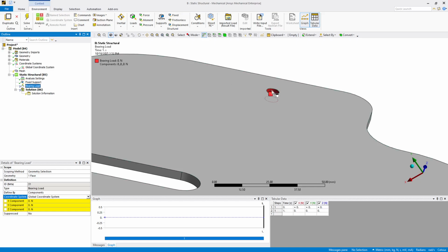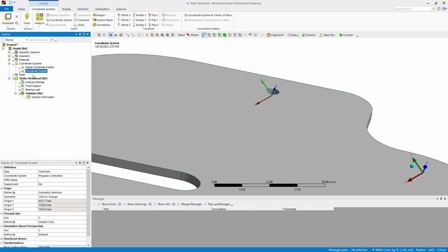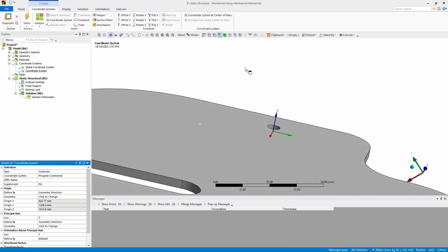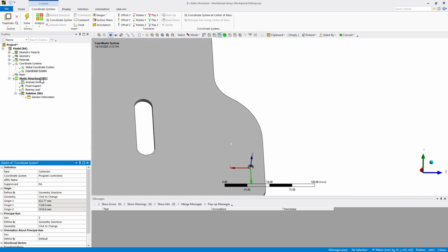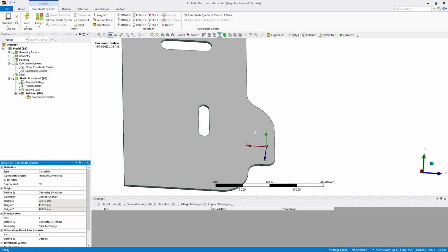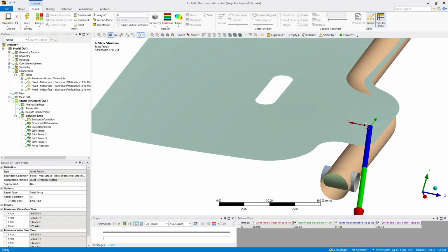So if I pick that face and insert a coordinate system and then orient the z-axis to be normal to some geometry, like this face here, we now have the same coordinate frame, except I need to flip z, and then X is toward the inside and Y is up, and that matches this joint coordinate frame where X is inboard and Y is up.